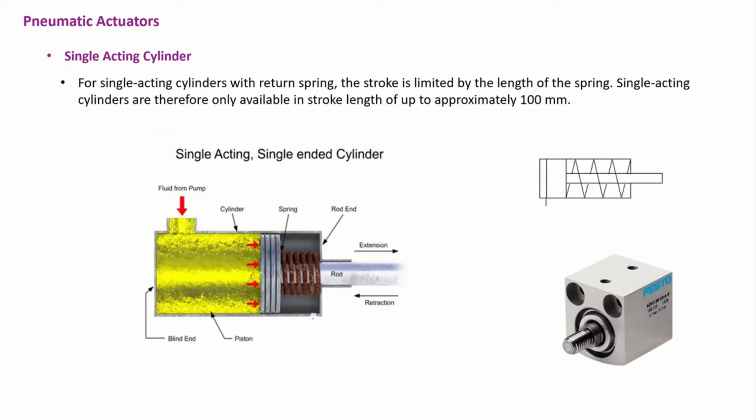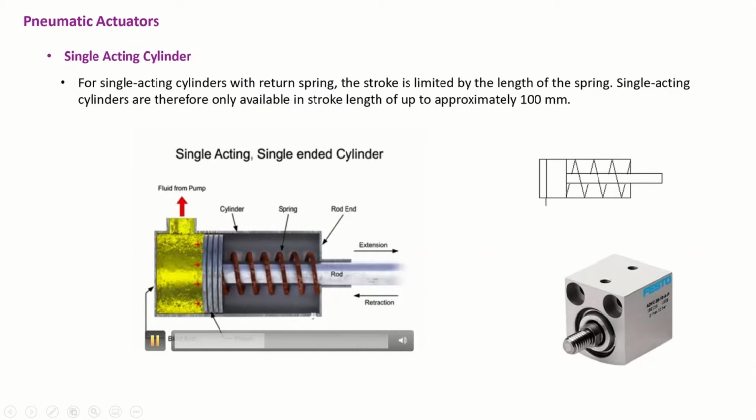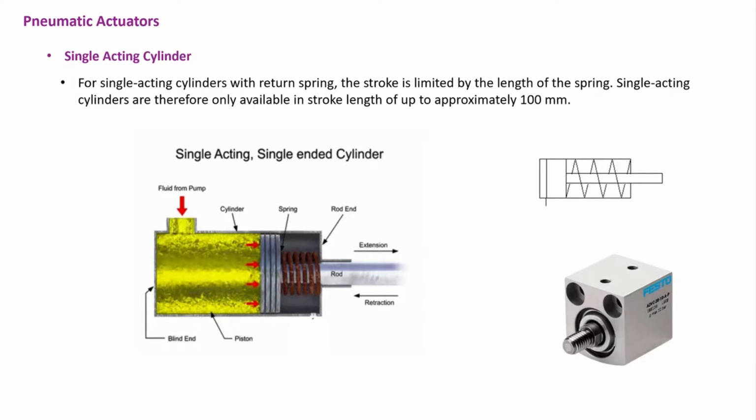Okay, so here we can see the single acting cylinder, and this video shows how the fluid is provided to the single acting cylinder from one side. When that fluid provides enough force, it overcomes the spring force, and from there we have the motion towards the fully extended position. Let's see this here. You see the fluid is coming.